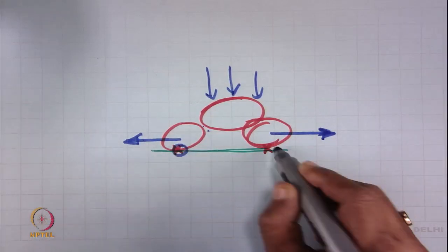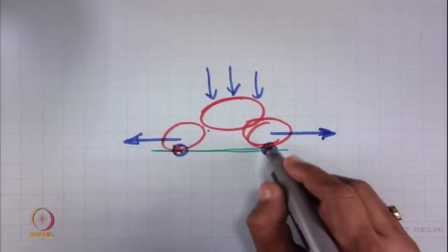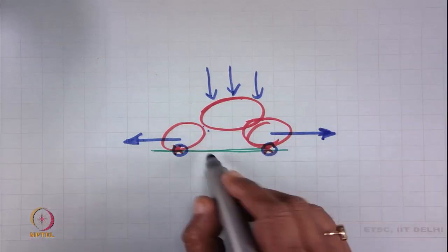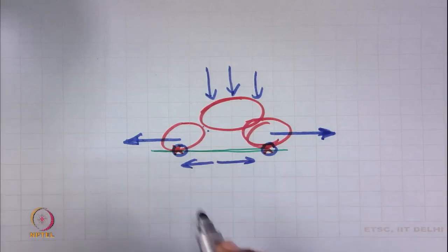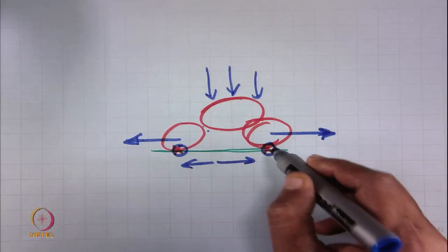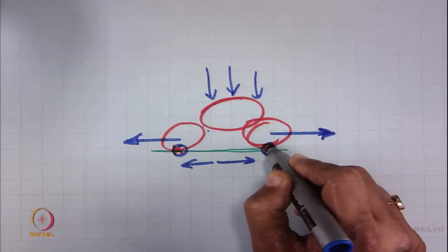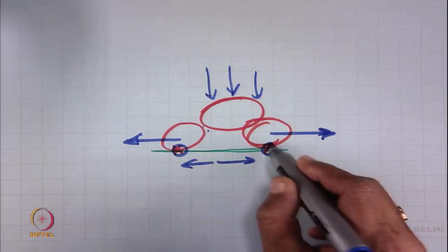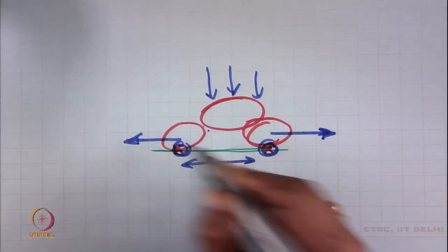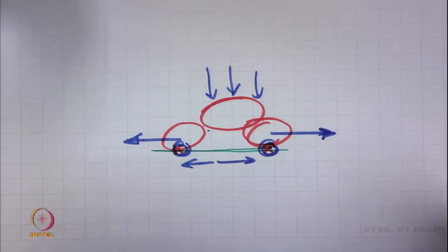Having these 2 gripping points, the geotextile will be stretched in lengthwise direction, and the gripping is not like wide width or narrow width tensile testing. Here gripping points are much less than the actual width of the material.